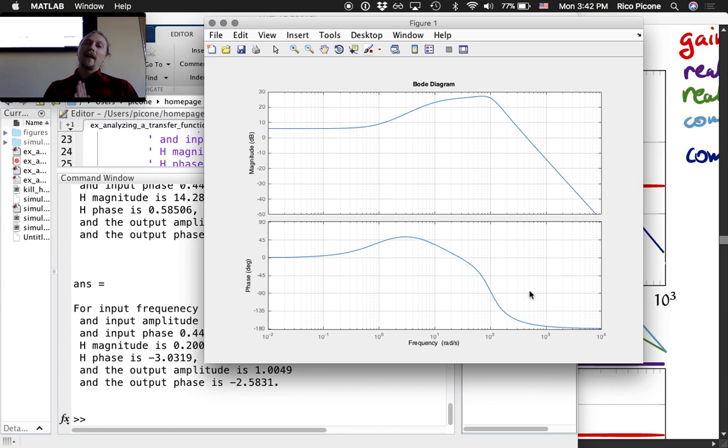If you're in a flat region, so if all of your acoustic stuff happens up here, you're fine because the phase is flat up there. But amplifiers, this is one of the things we often care a lot about, the volume or the magnitude of the signal, what the output amplitude is. But the phase can be a really important thing to worry about.